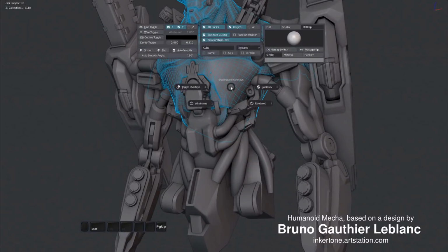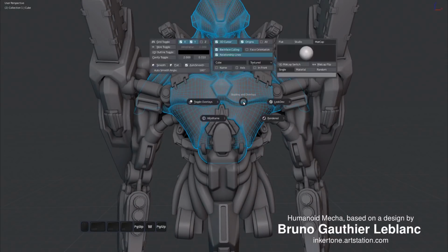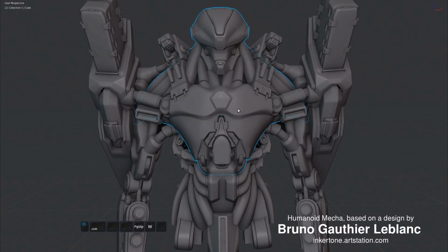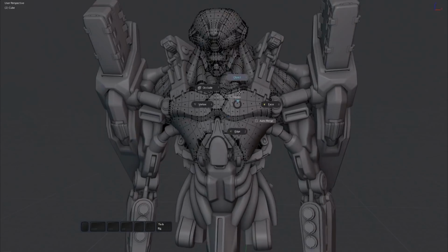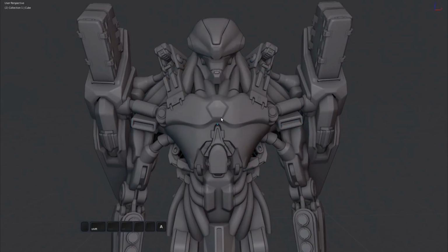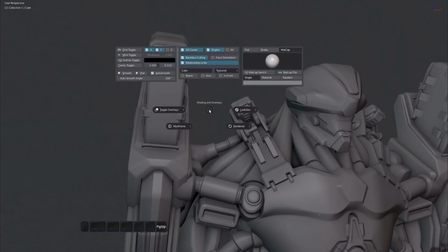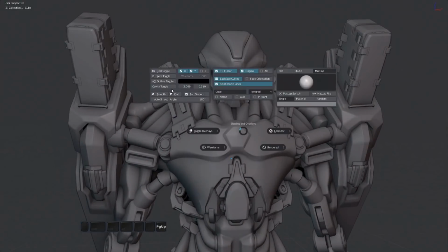With nothing selected, it will toggle the wireframe overlay. With objects selected, it will toggle the wire object property. And in edit mode, it will toggle X-ray. The outline toggle is extremely useful to make out mesh decals in untextured views, and is also great in flat or soft shaded views.